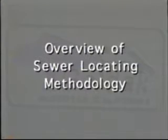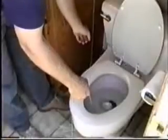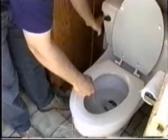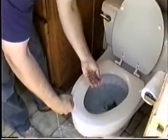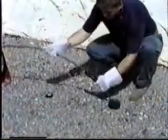Virtually all Goldak sewer locating systems use the same general principles to accomplish their tasks. In a typical application, a transmitter is inserted into the sewer line from some access point, such as a commode or a sewer cleanout. Once the transmitter is positioned in the place of interest, a receiver is used to scan for its location from above ground. The receiver can surmise the exact location, depth, and direction of the sewer line.